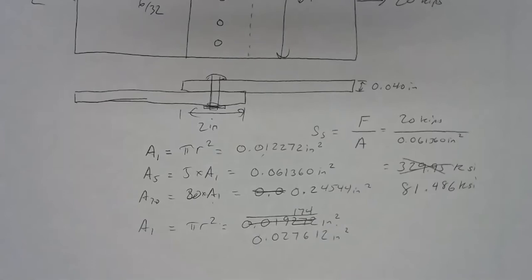And that gets us down to 36 KSI. Now that's above some alloys. Copper would work because copper has an ultimate shear strength of 38 KSI. Cast iron at 38 KSI. Brass at 50 KSI. We're still not quite down into the aluminum neighborhood here.